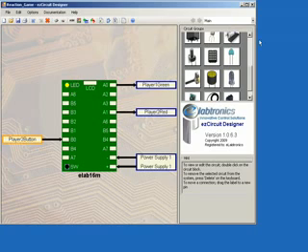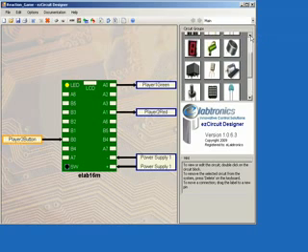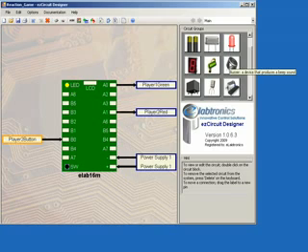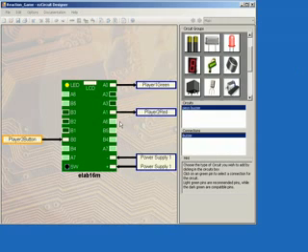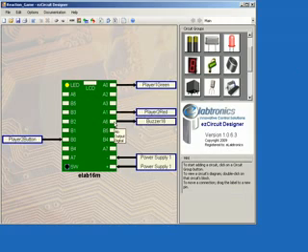We now want to add a buzzer by selecting the buzzer icon from the Circuit Groups menu and then clicking on the A6 pin. Once again, renaming by right clicking on the label, selecting Rename, and call it Speaker.